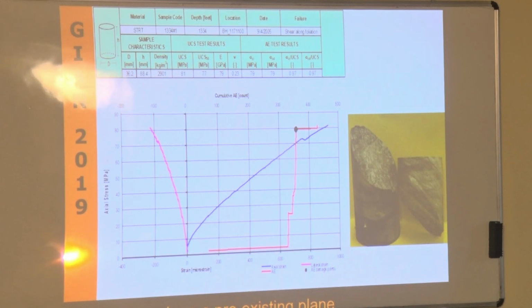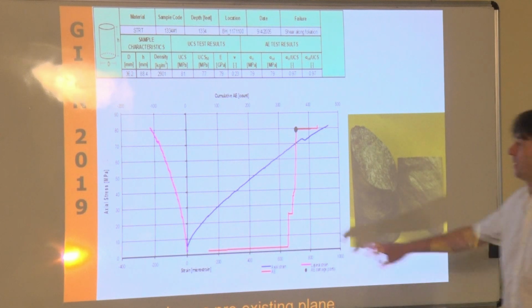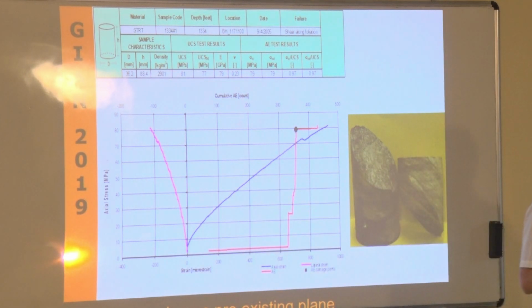For the simple reason that Poisson ratio is one of the values that is limited in any numerical model, but at the same time it's very subjective when you are going to calculate your Poisson ratio in a test. And that is one thing that you need to be very, very careful about.